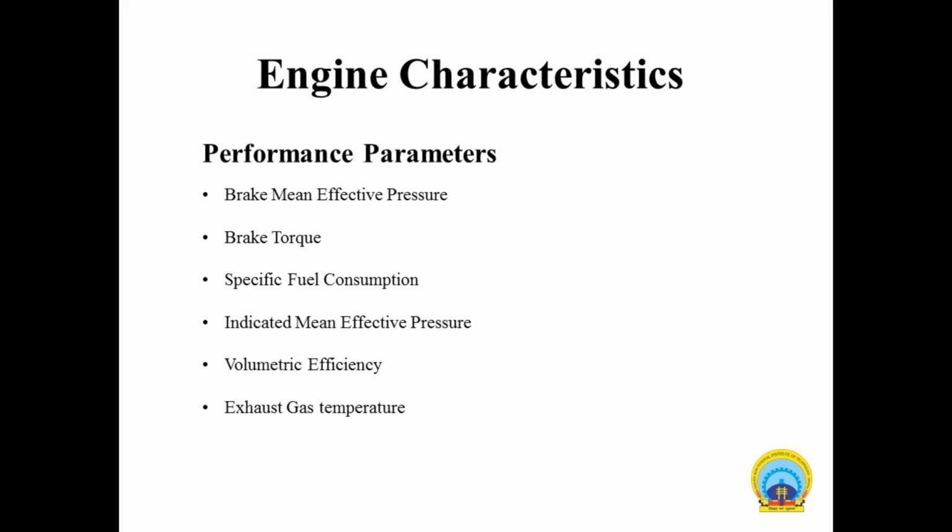These factors include altitude, temperature, and humidity. Aircraft engine performance decreases as altitude and temperature increase. In the case of high humidity, the volume of air available for combustion is reduced, so it will cause losses in power in the IC engine. In this, I have discussed only three parameters.